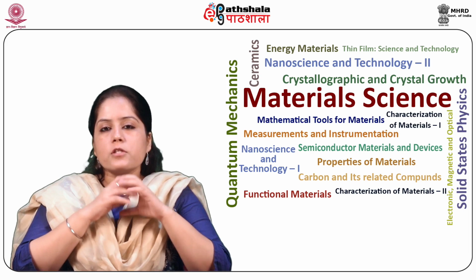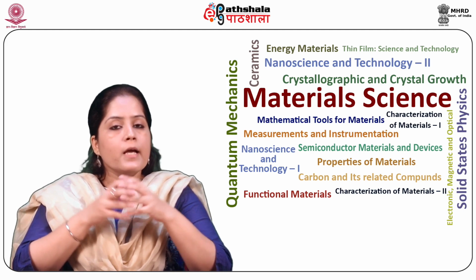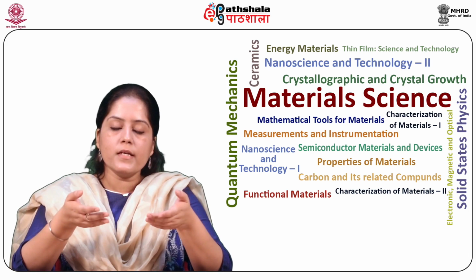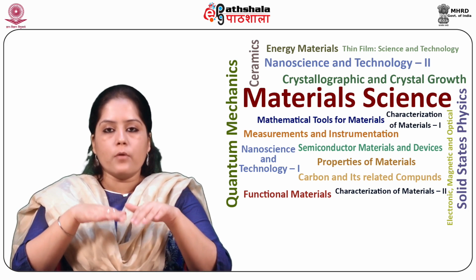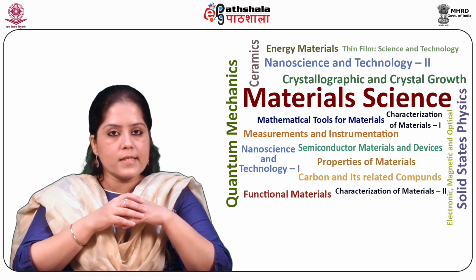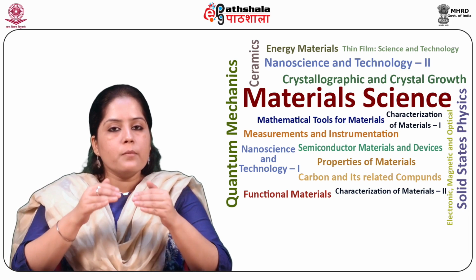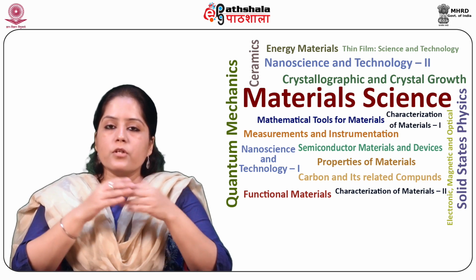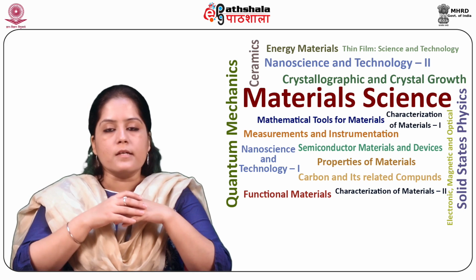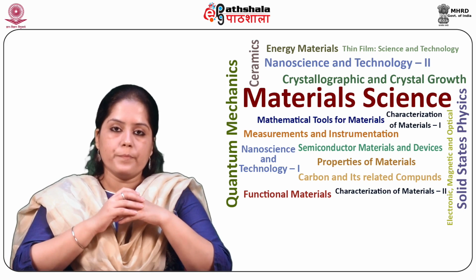For smaller devices, this is an important consideration, and as a result, most engineers make use of low temperature processes. However, in rapid thermal oxidation, thick oxide films cannot be produced, as it may generate stress in the film. Thus, for higher thickness, the diffusion furnace process is preferred.